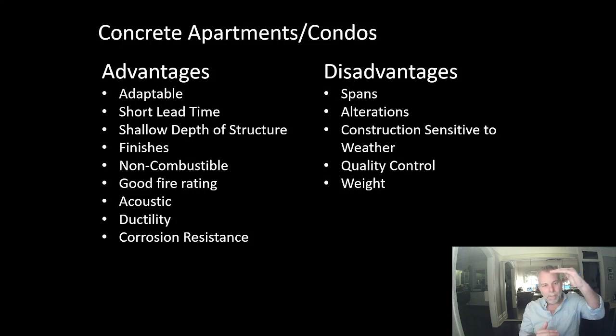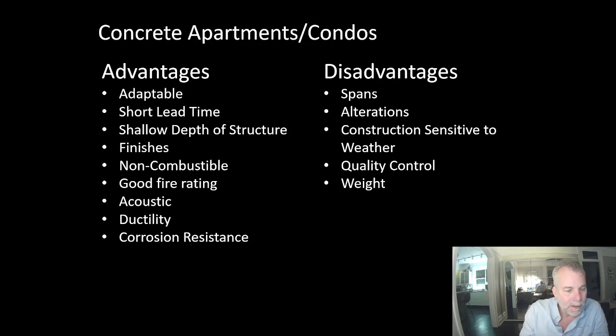Being deeper makes the system stronger, and one would assume that for a weaker material you need to go deeper. But in fact, a weaker material needs to be more robust. You need more material, and it can afford to be shallower, because it's governed by vibration and sag as opposed to bending strength. You cannot follow that logic without working out some numbers, but just understand that weaker materials generally can be shallower. Stronger materials, to get full utilization of them, often have to be deeper. They're lighter. Stronger materials make things lighter, but they have to be deeper.